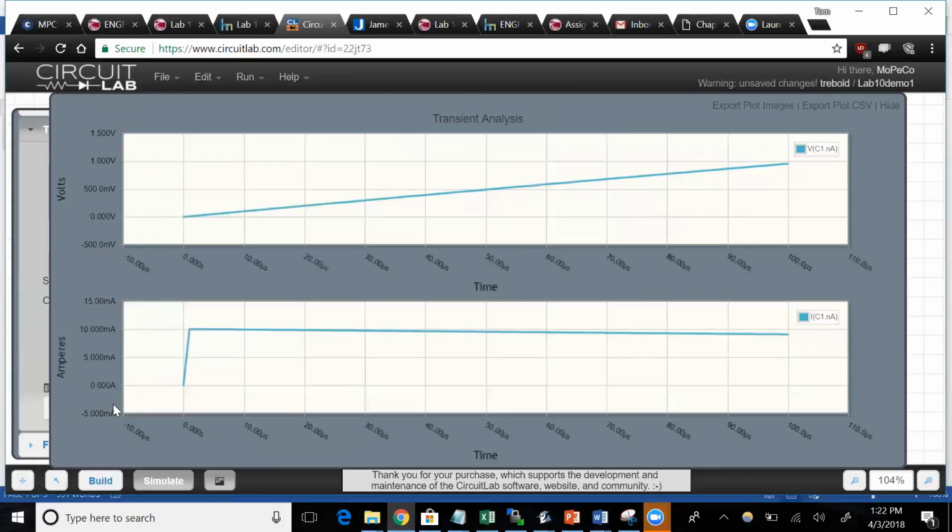And in general, what you want to do is go out about maybe 5 time constants in your simulation. It takes several time constants for an exponential curve to decay to close to its final value. So in your analysis, you're going to estimate what tau is. If you multiply that by 5, you can use that pretty much as the stop time of your simulation, because after 5 time constants, you should be close to your final value. Does that make sense? So 5 times tau is a good idea.